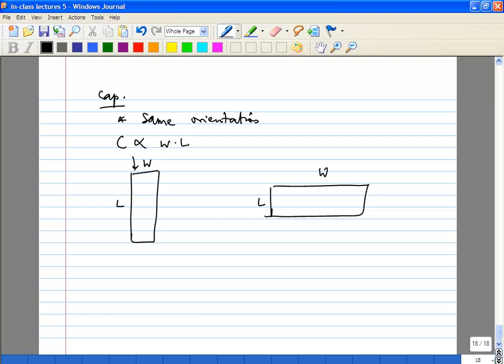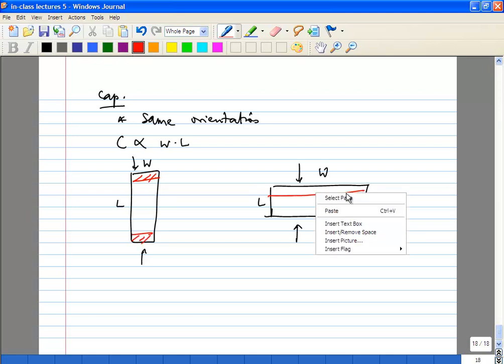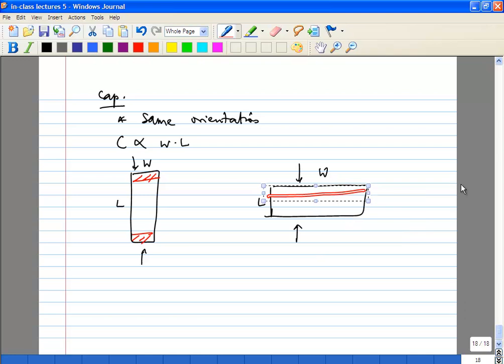Are you contacting them from this side, the two caps? So let's assume that's the direction. These are the two sides. In one case you would contact them like this, in the other case you would contact it like this. Which is better? The second one is better, obviously, because you have a much wider connection, so your series resistance is much lower. Typically if you have large value capacitances where you worry about the series resistance, definitely do this.